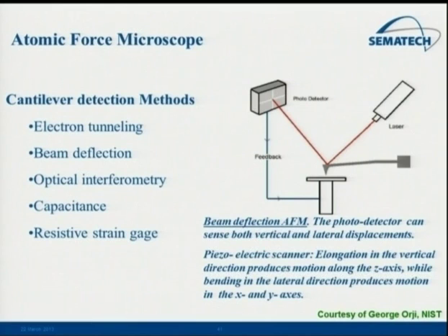It's called atomic force microscopy. What this is, and it sounds incredibly simple, is you have a small probe on a cantilever, and you drag that probe across the surface and watch how that probe goes up and down. Sounds fairly straightforward, but you actually can sample atomic level variations in the surface by this technique. So it's fantastic. This is the tool people use for measuring surface roughness most of the time.